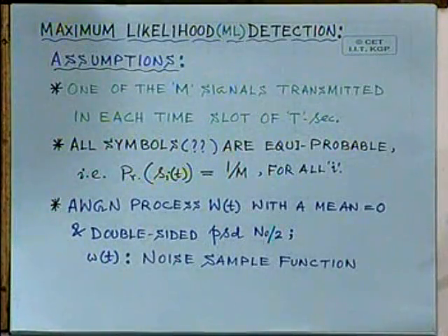Today we'll discuss the principles of maximum likelihood detection, which is a general and optimum method for detecting the transmitted signals, time limited signals conveying information through the symbols. And we will gradually consider a somewhat special class of communication channel where we have only additive white Gaussian noise, and the channel is a linear time invariant channel without manifesting any interference and other problems.